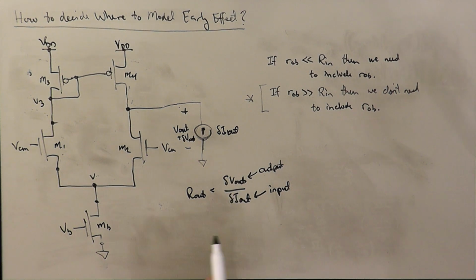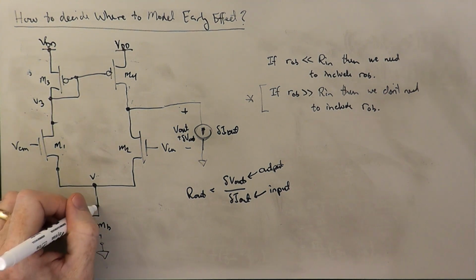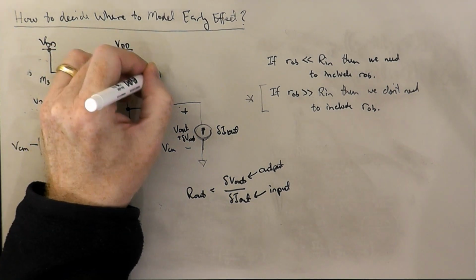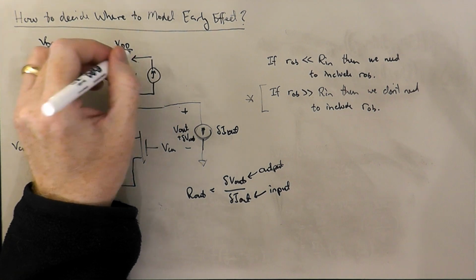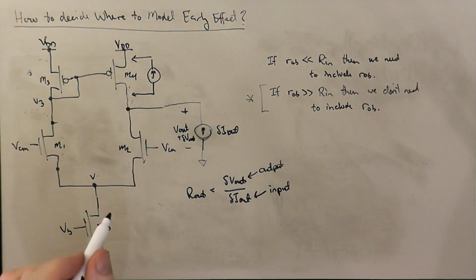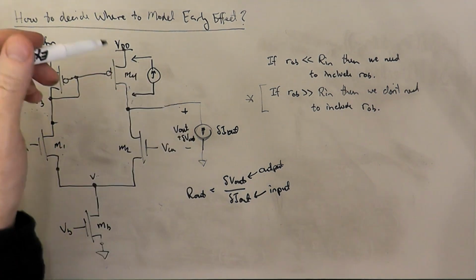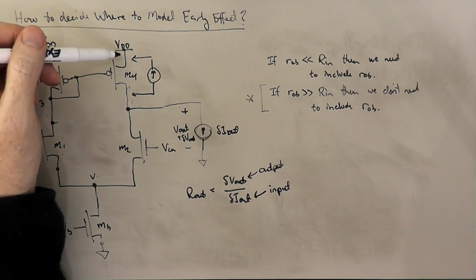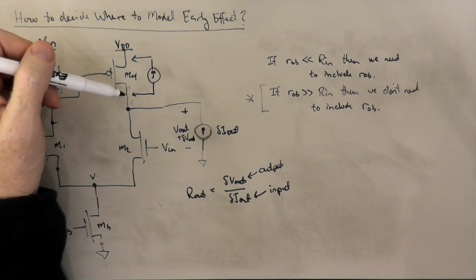Okay, so when it comes time to actually inject our test current here, when we split the source and inject onto the VDD side, of course, we're going to get the same thing. Nothing happens, right? Still injecting current into an ideal voltage source. The voltage isn't going to change across the transistor.